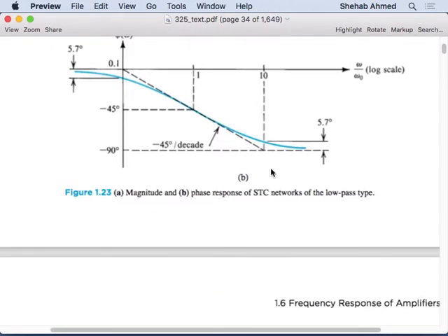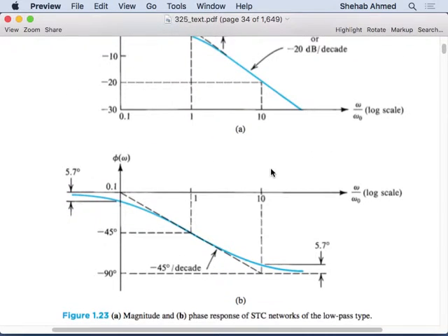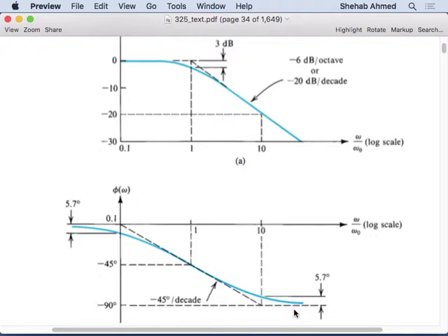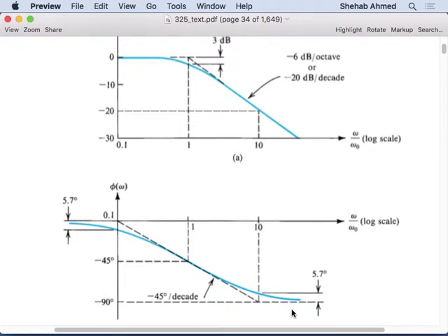Like here, it's 100 omega naught, right? At 100 omega naught, the phase shift was minus 90 degrees. Why is it minus 90 here? We calculate the phase. Remember, for the simple RC circuit, it was 1 over 1 plus j omega RC. So the angle of the number below was 90, for example, or was 85, or whatever. I had to bring that to the top, so it comes up with a minus sign. So there will be a minus 90 degrees phase shift between the signals.